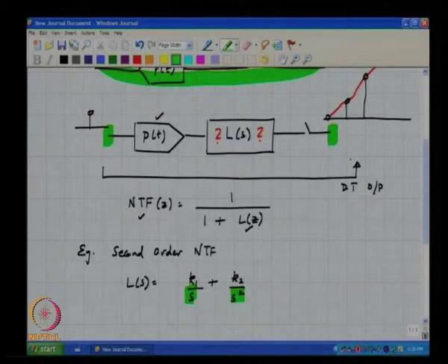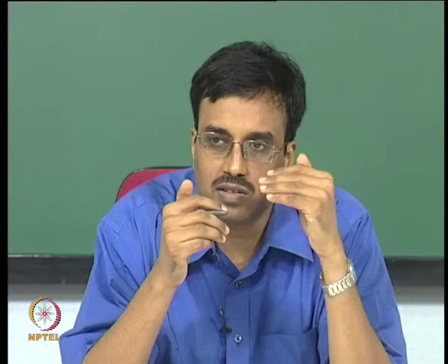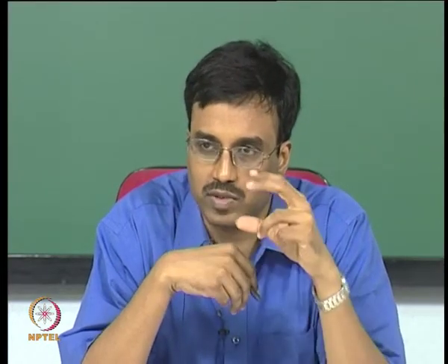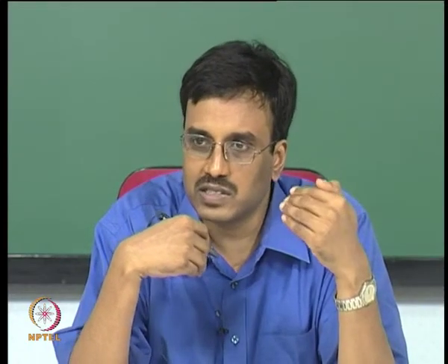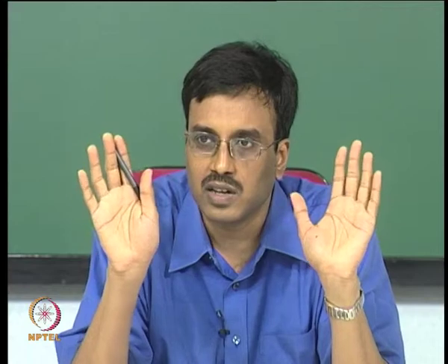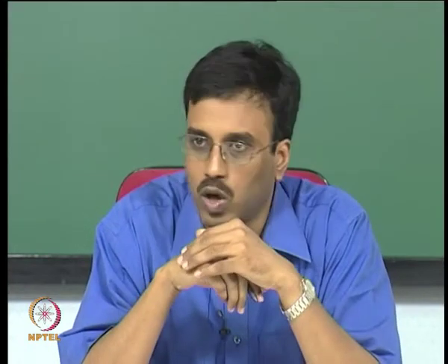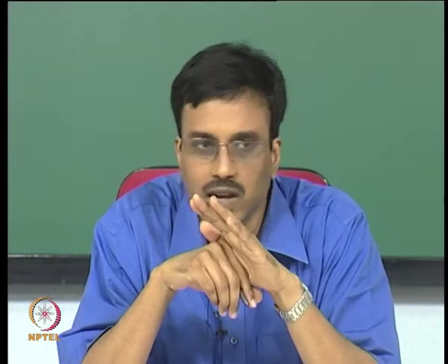The only thing we are worrying about now is placing the zeros of L of S such that it matches L of Z. So, if the solutions do not match for any two choices of equations that you choose from this infinite set, all that it means is that this choice of poles is not appropriate, that is all. Is that clear?